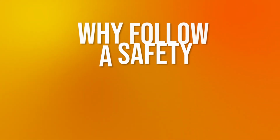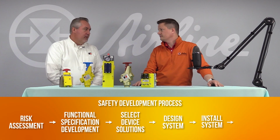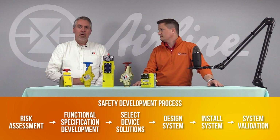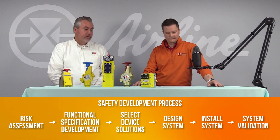So Chris, why should companies follow a safety development process? Well, a safety development process creates a systematic process that starts with a risk assessment and leads into something we call functional specification development, which defines how the system needs to operate and run in every mode of operation. That functional spec then leads to selection of mitigation devices or risk reduction devices, and then leads into the design and then ultimately installation and validation. And so your validation should always check that everything identified in the risk assessment has been properly reduced.